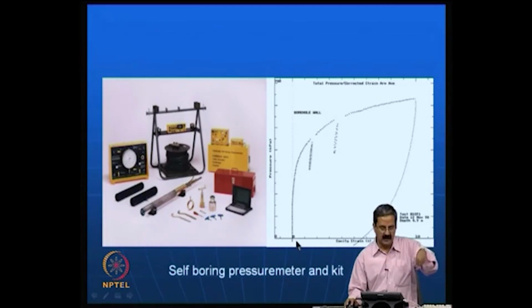These things are all based on cavity expansion, there will be oil, and then you apply some pressure, the cavity expands, and there is a cavity expansion strain you are trying to measure, and so this is the loading portion, and then this is unloading.